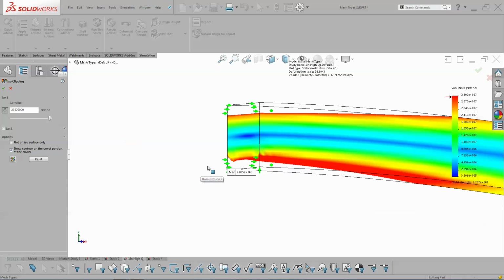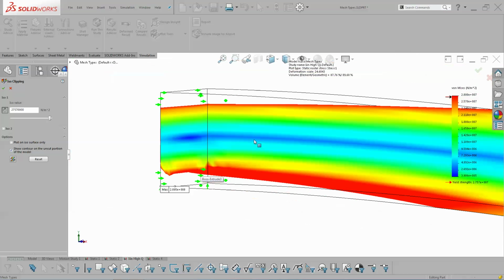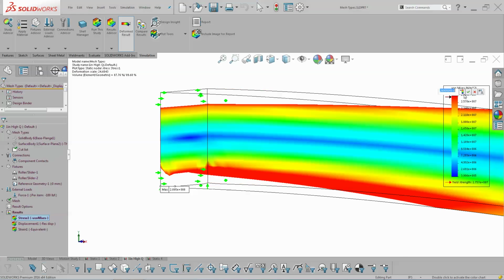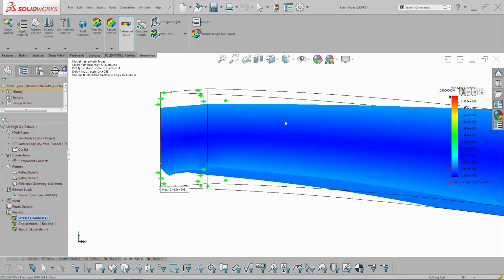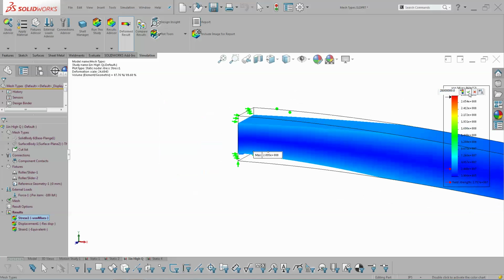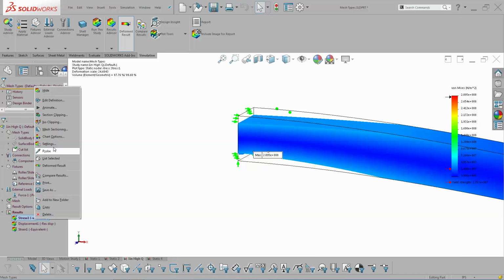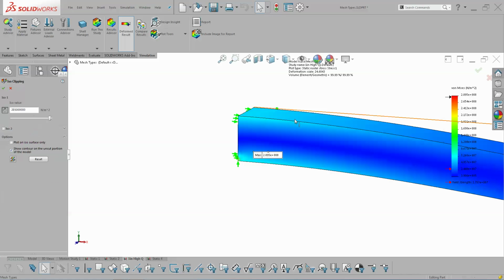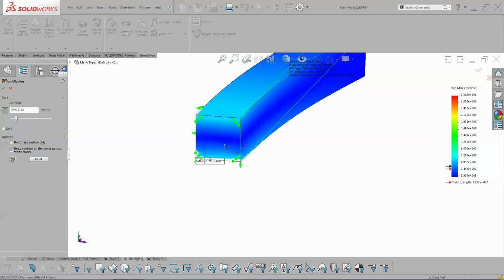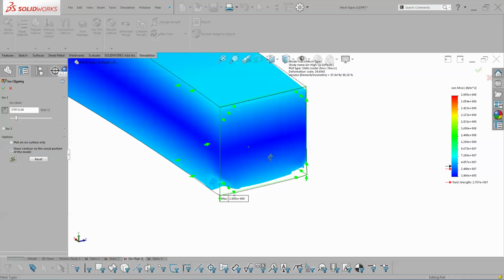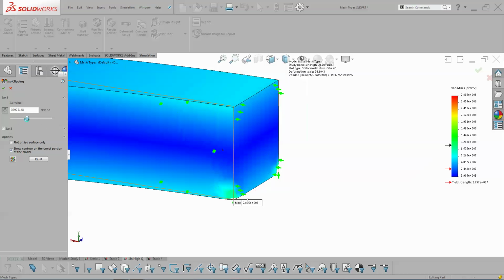So if I go back and do another iso clipping, I've just increased the scale back to its full amount. And what I can do is pull this down and see that for a long time, we really don't lose any information out of the corners. And that's because of how highly concentrated that stress singularity is. So this might be enough for you to begin to ignore that stress singularity if this is a simple run of your simulation and you just want to see the overall results. But definitely take a look at that.